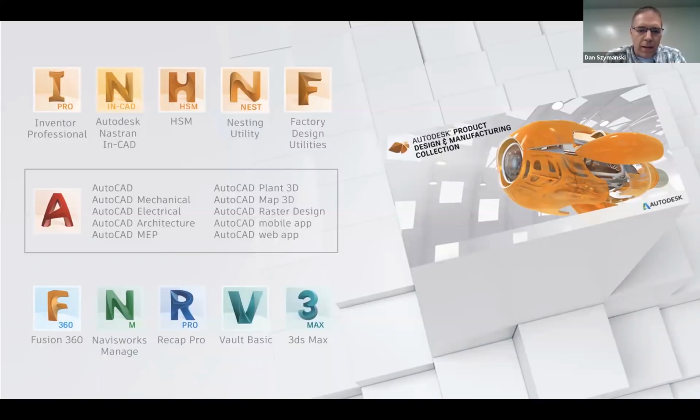So also Jerry asked, how is Unwrap beneficial when it doesn't take into account expansion, contraction of material, similar to stamping a sheet metal part? So that's exactly the use case. When you have an extreme deformation and you're using a standard modeling practice that does not leverage the standard sheet metal bends or folds, there was just no workaround to actually obtain a flat pattern from that. It was very difficult to extract that.